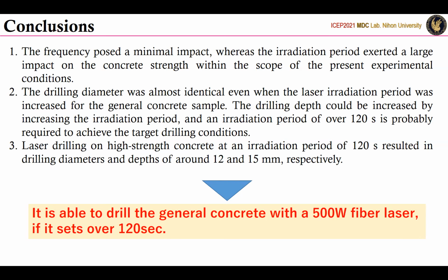Second, the drilling diameter was almost identical even when the laser irradiation period was increased for the general concrete sample. The drilling depths could be increased by increasing the irradiation period, and an irradiation period of over 120 seconds is probably required to achieve the target drilling conditions.